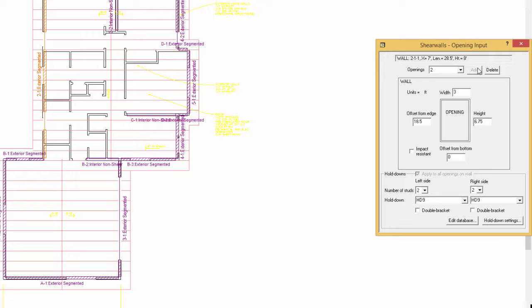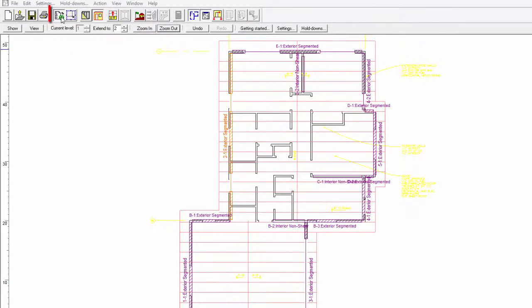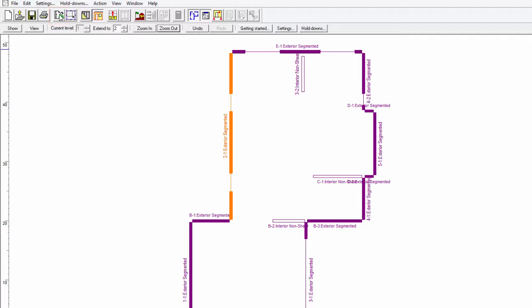To ease viewing, click on the Import CAD Drawing button and the layout will disappear. You can turn it back on at any point during the design. Click on the Extend Walls button. This automatically creates the upper level walls for the blocks with multiple levels. To view the current openings, click on wall E1 and select the Elevation View button.